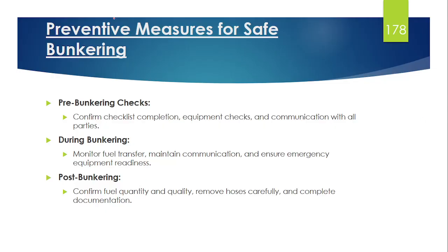Now, as I told you the whole thing, let's sum up everything. So pre-bunkering checks need to be ensured by checklist. In order, we should check the equipment, we should check the communication, and we should check the alarms. During the bunkering, you should make sure that you are properly transferring the fuel from one point to another without any leakage, you don't have any irregular sounding in other tanks, you have proper communication, and your emergency preparedness is in ready condition.